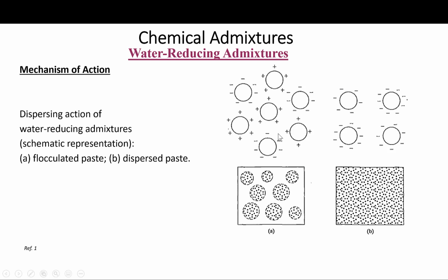The cement particles here basically flocculate and tie up the water molecules between them. When the cement particles are charged with a like sign, they repel each other, and the water is freed basically to participate in the reduction of the viscosity of the paste. So, as a result, more of the water is available to reduce the viscosity of the paste, and that basically increases the workability of the concrete. These surface interactions are most noticeable with the fine cement particles and the mineral admixtures, since the